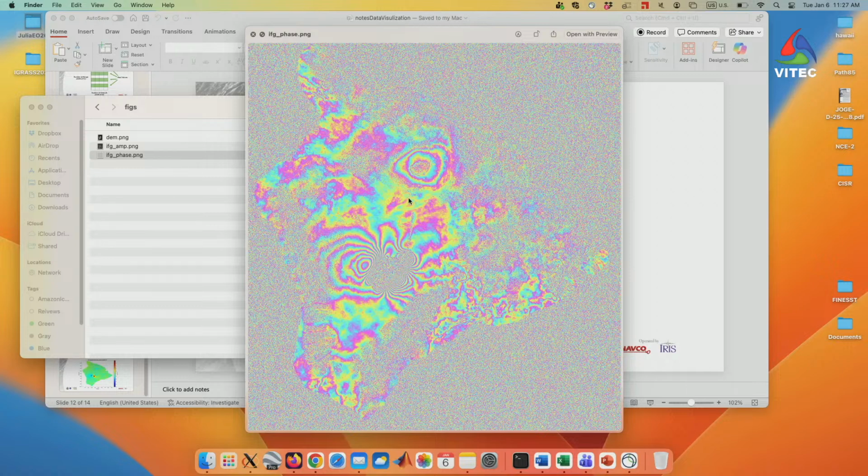And also the other feature you can see is this one almost looks like a topography feature. It's not, because the topography fringe is already removed. So this is just because there is some local topography and your tropospheric delay along your satellite signal path. To the top of the mountain, the path is shorter than to the bottom of the mountain, right? Plus, there is additional water vapor, things like that. So you will see some of the tropospheric features that look just like topography.